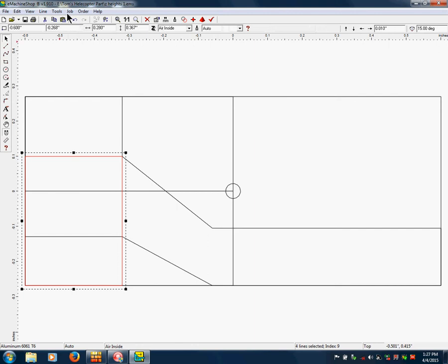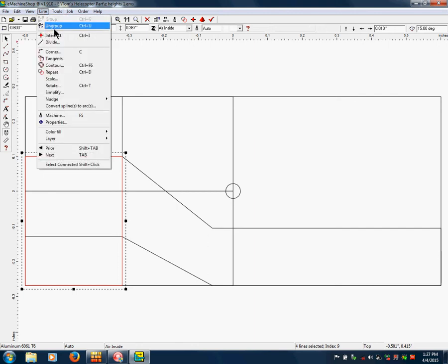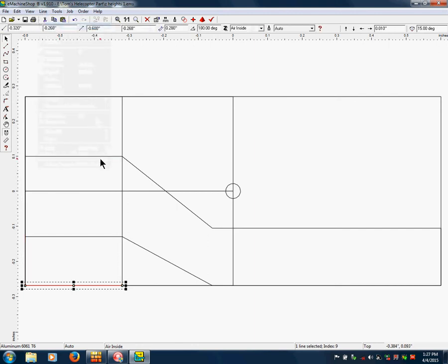It'll release before then. Let's go line ungroup. Select the top line. It's going to release before it gets to this depth, but that's 0.099. So we got 0.269 down to 0.099. That's the final Z depth of cut.